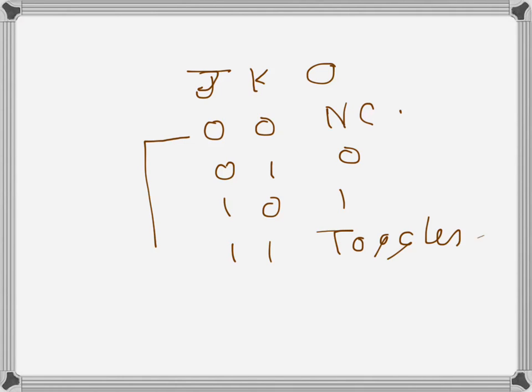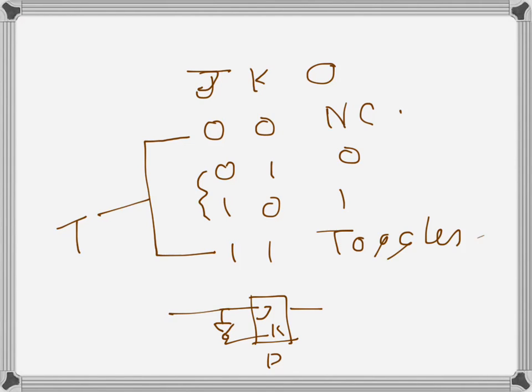So when we look at these two inputs, that means when J and K are connected inversely, with an inverter here, it becomes a D flip-flop. We know that, and so this becomes the input of the D. And if J and K inputs are just tied together, that's J, that's K, that's output Q, it becomes T.